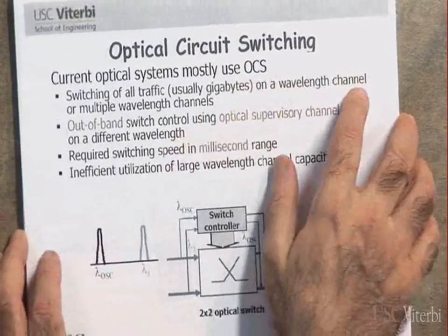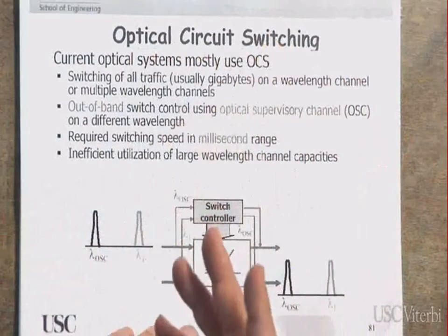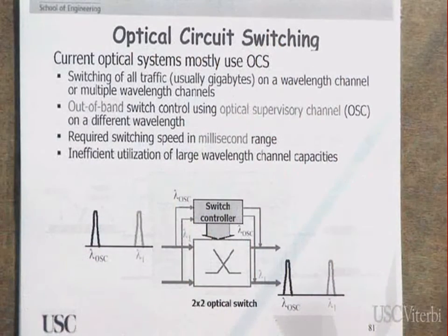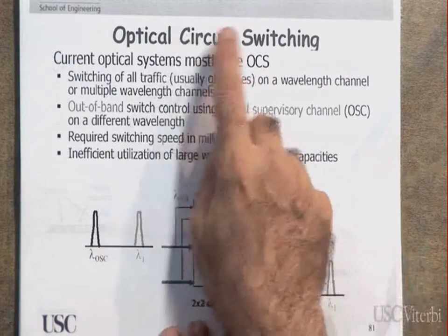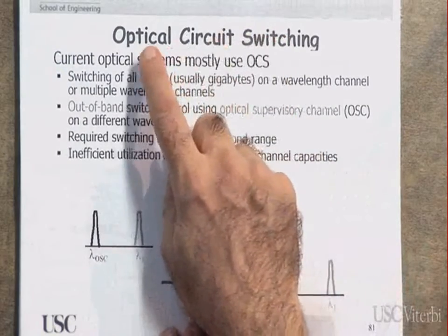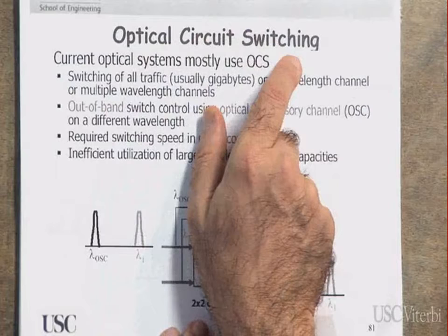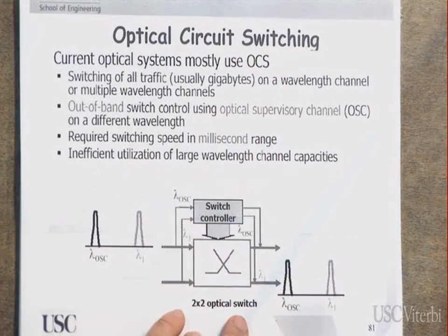What they are proposing, or what they are working on, is what is known as optical switching, which means everything will be done in the optical domain, rather than changing it to electrical. Now, in an optical circuit switch, most optical switching currently is circuit switching. What is the meaning of circuit switching? From port 50, in a circuit switching, the circuit is going to be what?